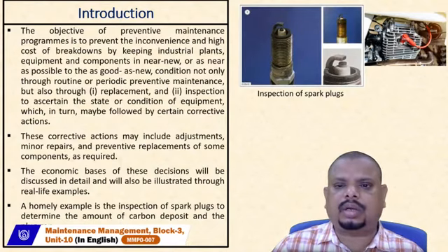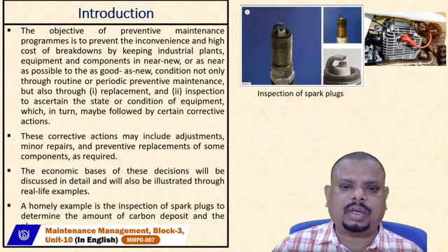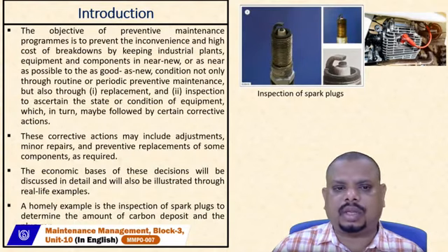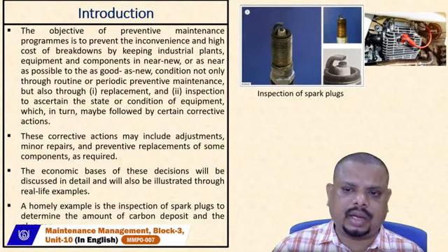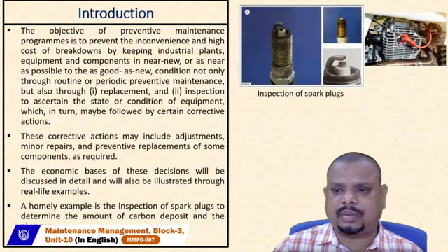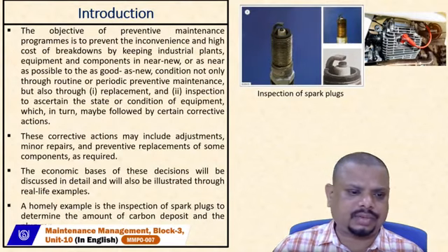So if required, we must go for replacement, and if not required, in those cases you have to apply preventive maintenance so that you can clean the carbon deposit from the top layer of the thread, and similarly it increases the potential functionalities of the engines during the ignition stage.